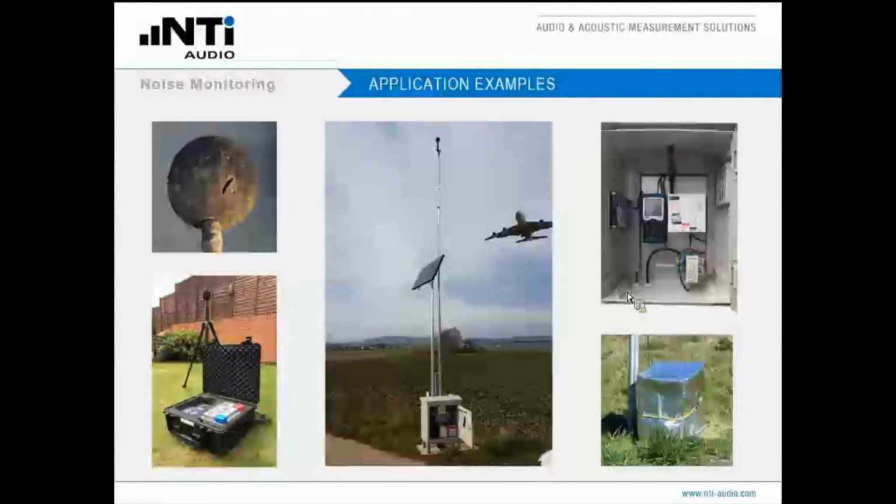These are some examples of actual setups out in the field. Here you see such a microphone that has been attacked by a bird. You see deep cuts here in the foam. You see the bird spike has been broken off. So it is advisable, as we said here, it's not set clearly, but that you place the microphone aside of the pole tip.